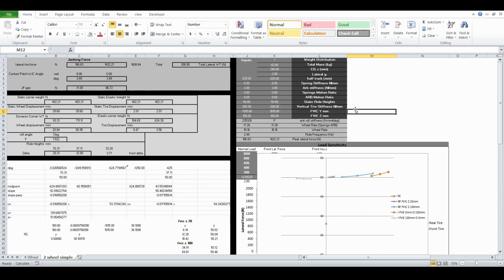I think an example of what I'm talking about might show better the effects of inside versus outside tire jacking force. So right now they're both left and right, the instant center locations 100 millimeters up. We can look at the roll angle, 1.522. So we'll put the inside tire's instant center down to 0. So jacking force goes to 0. And the roll is still 1.552. So it changed a little bit, but not a whole lot.